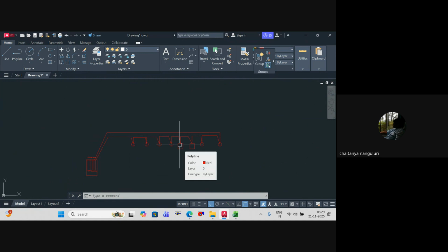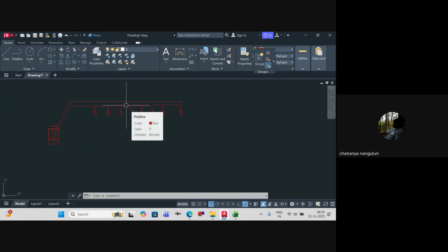From the fire alarm system, you have multiple detectors and modules which will be going back. In each loop, you can have up to a certain number of devices, depending again on the model. Generally, the source voltage is 24 volts. In olden days, it used to be up to 99 or 100 devices, but nowadays you can even connect up to 200 devices, is what OEMs are telling. So 100 to 200, depending on the model, in each loop.